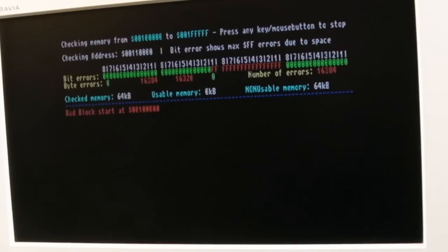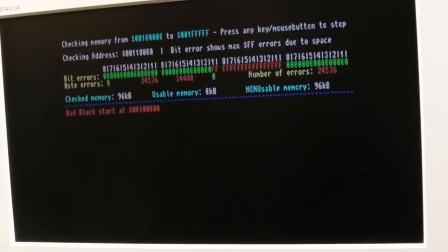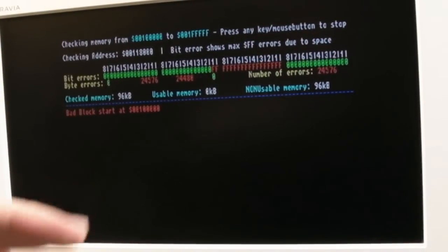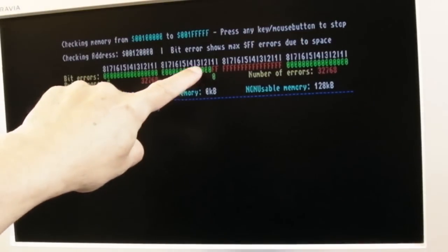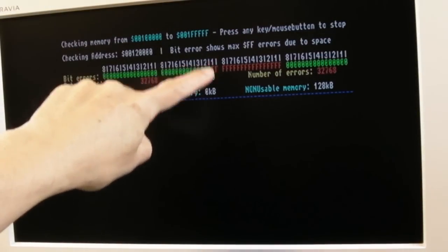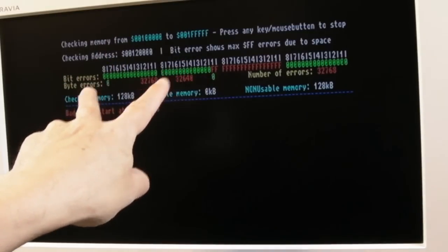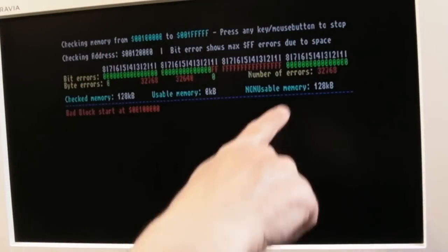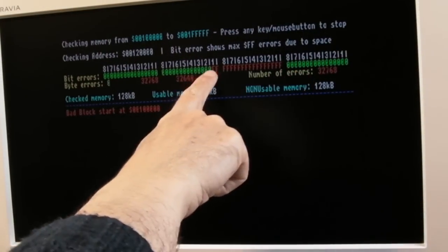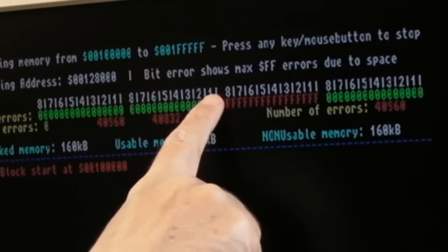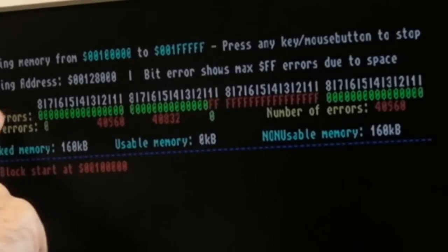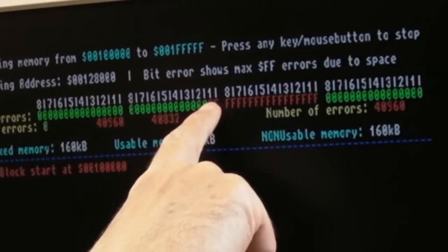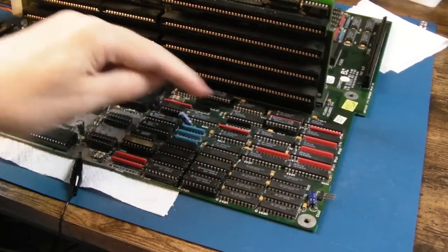Right, so I'll talk a little bit about what I've done here. I've just checked all of the control signals on the 245s and the 74F646s that sit in between the two banks of RAM. In particular, I'm paying attention to bit 1 on the upper word. You've got two 16-bit words here: lower byte, upper byte, lower byte, upper byte. So this starts here at D16, and you've got D31 over here. That's D16, and I've done the usual connectivity tests.